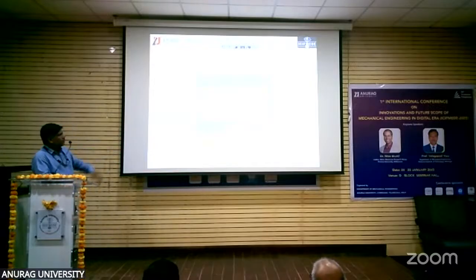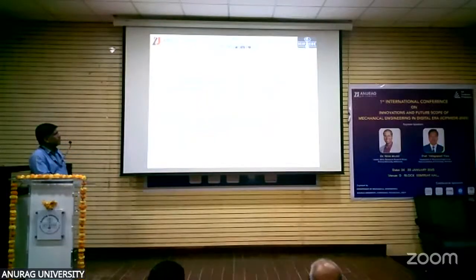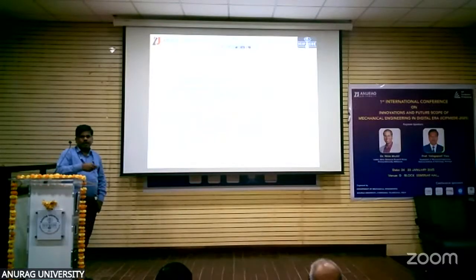So it will start from here. Once you enter your information, it will show whether a reheater is present or not. Once the reheater is selected and you click OK, the start button will appear. Once you click the start button, you can start entering the data. This is very important for collection of input data, and that is very important for evaluating the performance of the boiler.